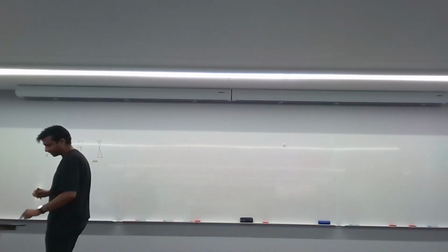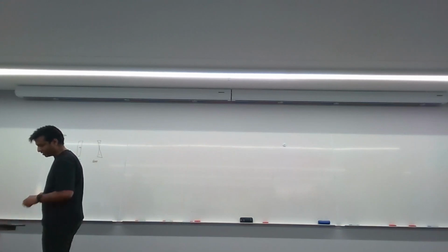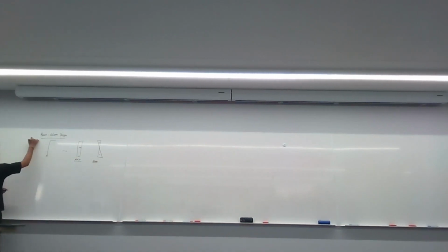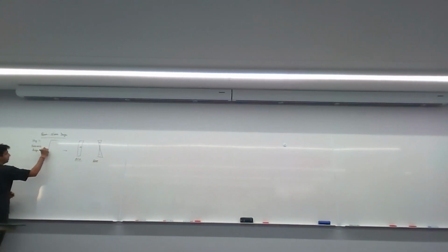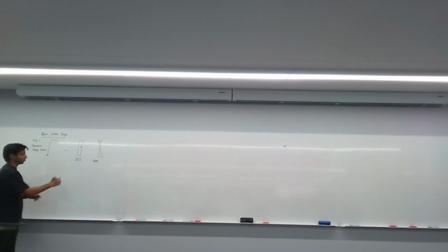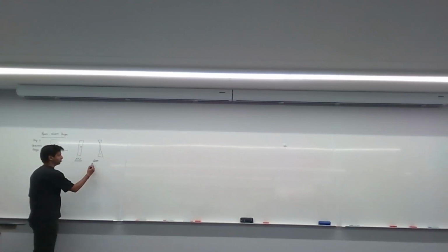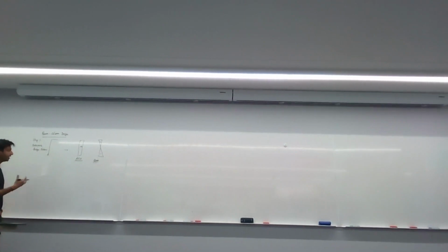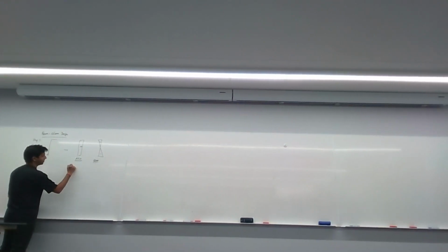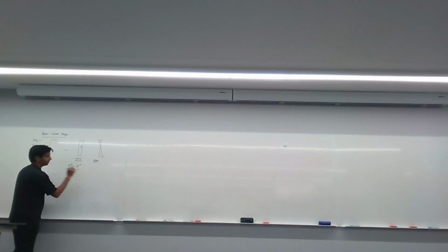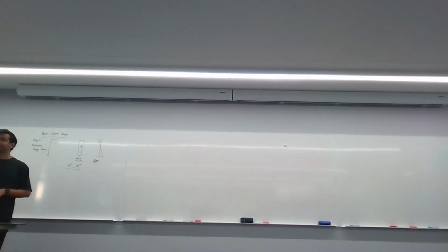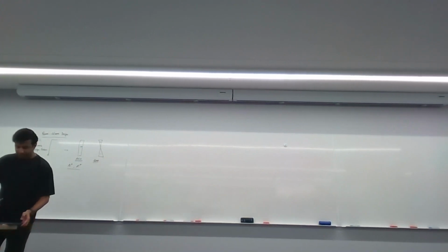So the first step is to determine your design actions. This is step one: determine design actions. What does that entail? That entails drawing out your axial force diagram. That also entails drawing out your bending moment diagram. What that also means is I want N star, the axial force that we're going to use, and M star. These are the values that we need. This is the design action for your values.